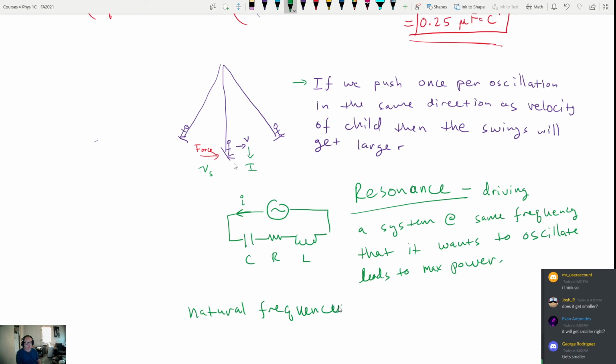And we can figure out exactly what this quantity is by thinking about the LC circuits that we looked at in the past. The LC circuits had a frequency of the square root of 1 over L times C, and these RLC circuits have the exact same natural frequency. Sometimes this is referred to as omega naught. This is the natural frequency of the system.